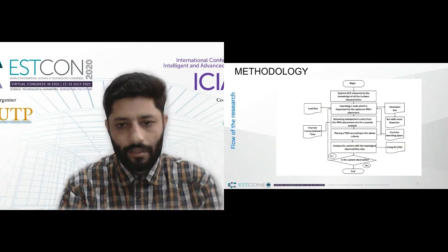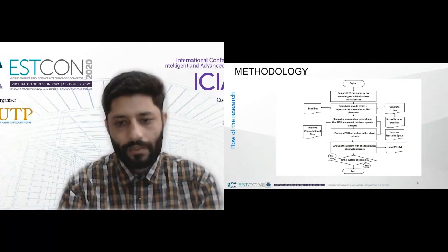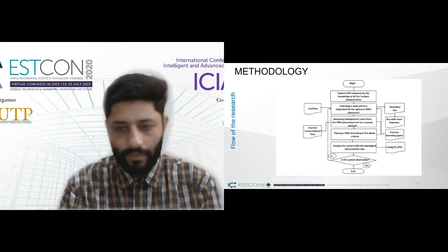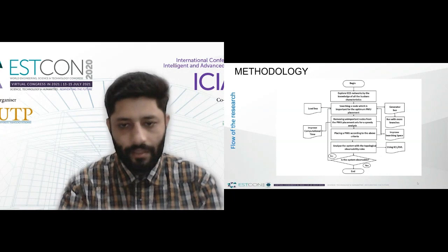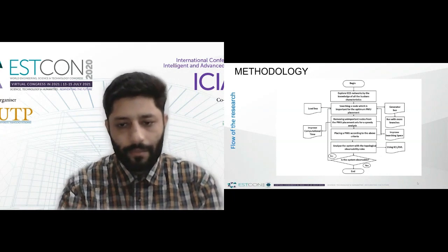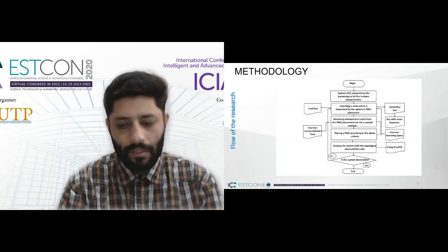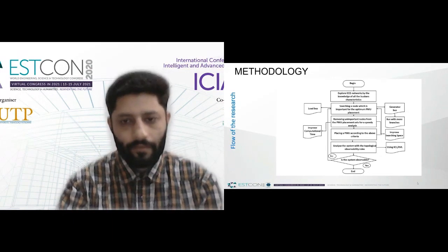And then we place a PMU according to the above criteria mentioned about the load buses and generator buses. And then we move on towards the analysis of the system with the topological observability rules. These rules use the KCL and KVL laws by placing the PMU in a network. As we have mentioned in the second slide of the introduction, the placement of PMU should be in such a way that it will cover the whole network by using the KCL and KVL node equation. The example has been given in the second slide of the introduction.